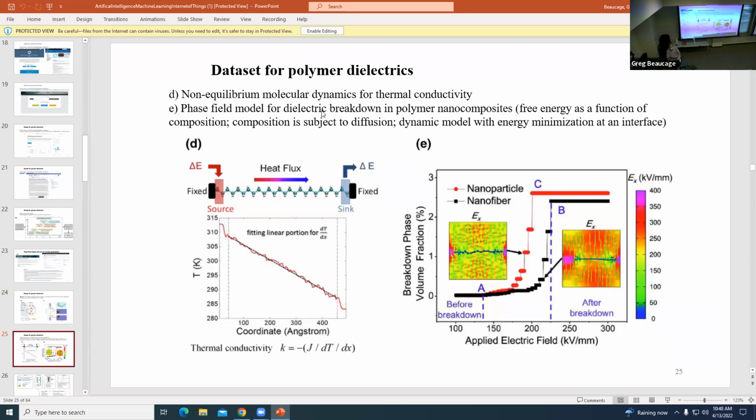And then there are data sets for the dielectrics. I guess this is showing that this heats up. When electrons flow through, it's going to make heat, so you need to model the thermal behavior of these things. This is just showing an example from a paper that they did. This is dielectric breakdown. You can see it's conducting at some point, and not conducting at the other. As you increase the field, there's this breakdown voltage. That depends on your use environment, what that is. You can spec that cutoff.